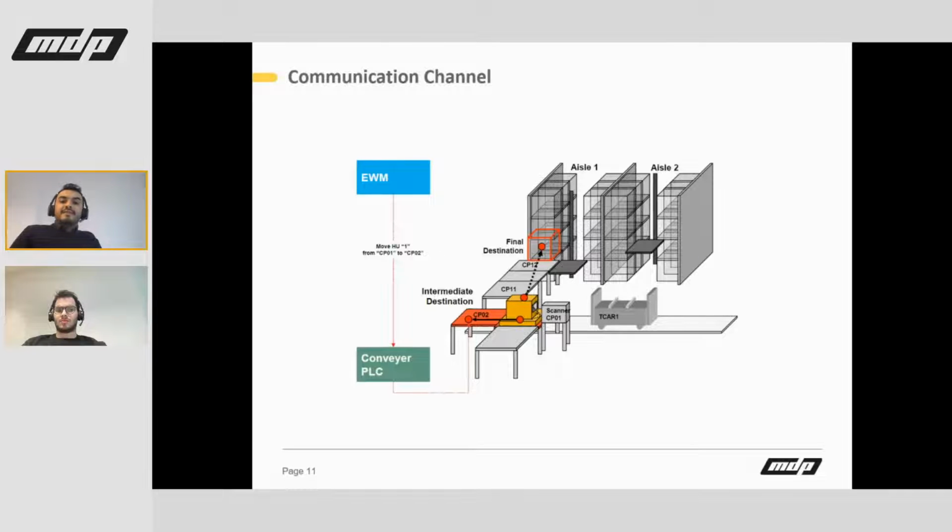So to facilitate this communication between MFS and PLC, a communication channel for a specific PLC should be defined, and in the process, certain properties such as length of the messages, whether the confirmations are to be used or not, should also be defined in order to send and receive correct telegrams using these communication channels.